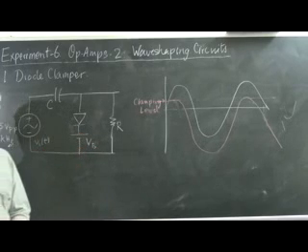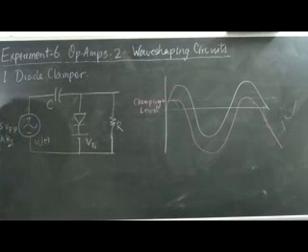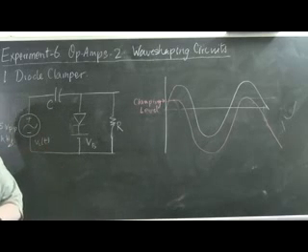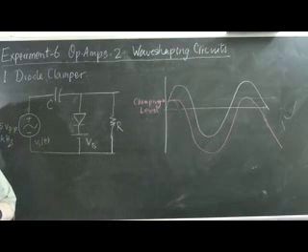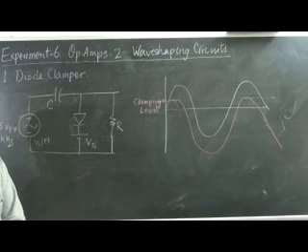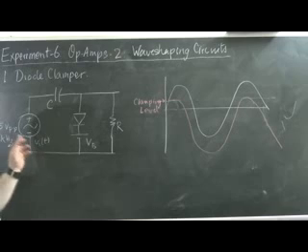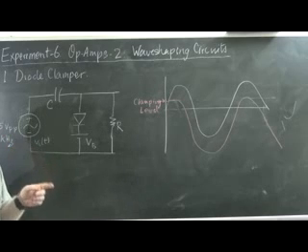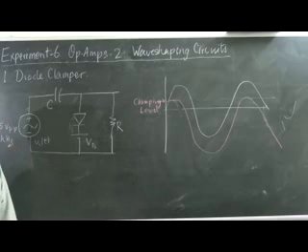So all you need to do is to exhibit the input and the output waveforms on the two channels of the oscilloscope, making sure that the output waveform at least is watched in DC mode so that the DC shift of the output is clearly seen with respect to the input. Ideally you should put both the input and the output onto the screen in DC mode so that you can see the DC voltage difference.